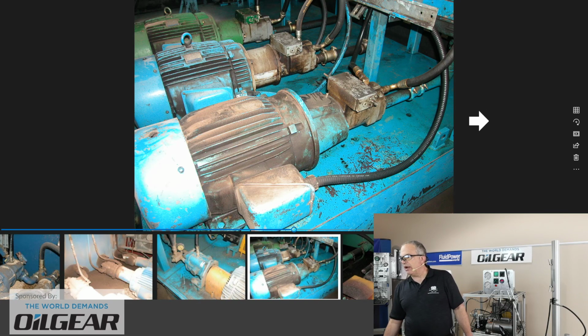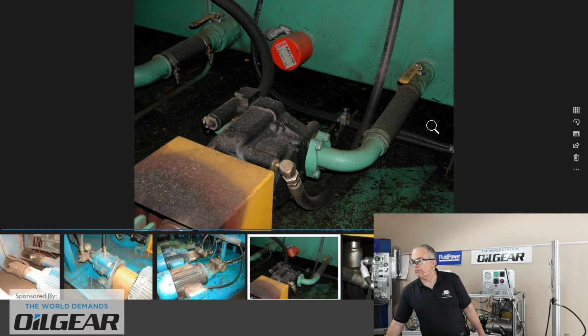Here's another style, Oil Gear with transverse types of controllers across the top of the pump body, and that's another way of arranging. And you can see a couple of adjustments, one on one side sticking out and one from the other. Okay, so a couple of adjustments there, and we'll get into those and what they mean in a moment. Here again, it's a fairly simple pressure compensated piston pump with a single adjustment pointed towards the shaft end.